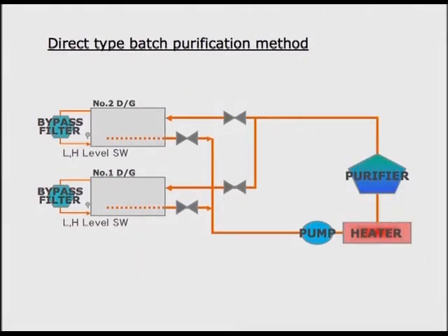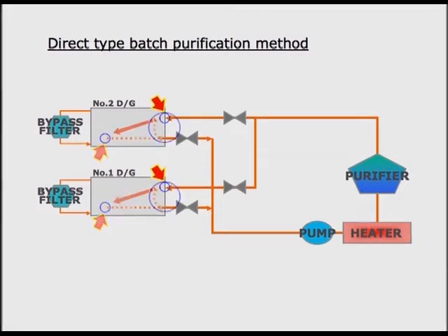In case that there is no settling tank and the method accordingly requires you to conduct the cleaning treatment by connecting the sump tank with the purifier one-on-one, make sure that the takeoff position of lube oil is distant from the return position. You cannot obtain the cleaning effect if the takeoff position and the return position of lube oil are too close together.